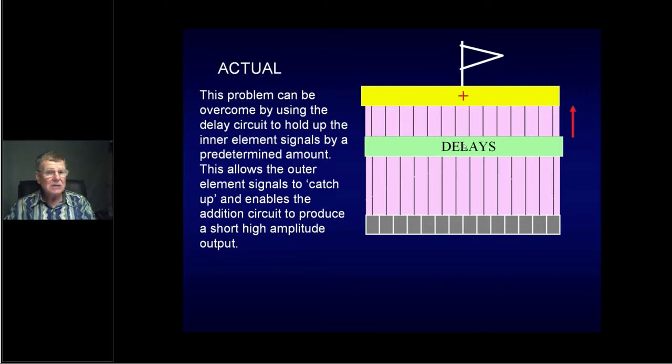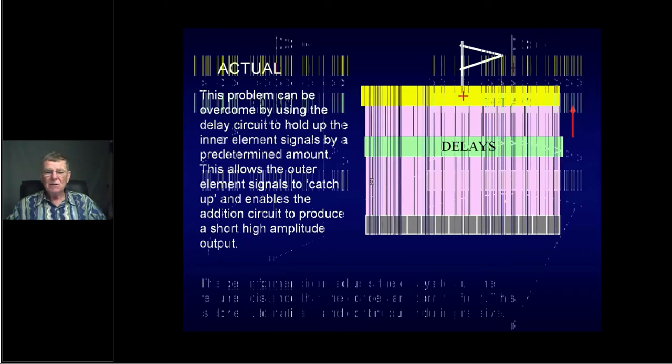But to set the delays correctly, the machine would have to know the radius of curvature, wouldn't it? Logically, it does. The radius of curvature is the focal depth, or the depth that the echo came from. The machine knows where the echo came from. It's done the timing. After all, it's going to put that echo in the right point on your screen. So the machine knows from its timing what that curvature is, automatically sets the delay accordingly, and gives you the best signal. So as the echoes come up from deeper and deeper, the delays are automatically adjusted less and less to maintain that signal.